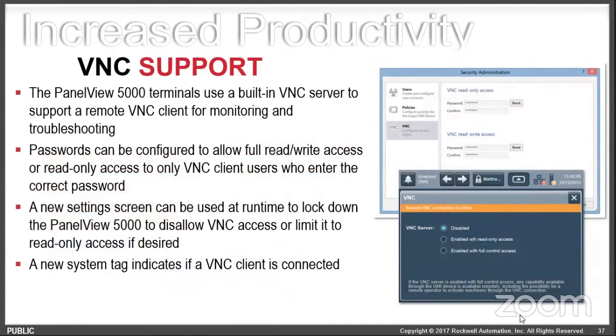VNC support, we talked a little about that for the PanelView Plus 7. This works the same way, where there's a VNC server built in, you can turn it on, and you can set read-only access, write-only access, all that security stuff, because you don't want just anybody going in there and seeing what's going on or making changes. There's also a tie-in with ThinManager, where you can see that content and mirror it through ThinManager. So Michael, we'll talk about that a little bit later on.